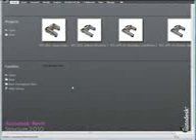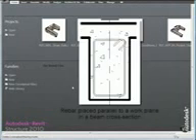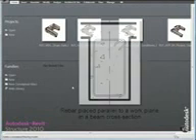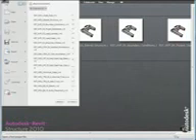In this lesson, you will place rebar in a cross-section view. The rebar is placed parallel to the exterior face of the concrete beam. Click the menu browser and select Open.